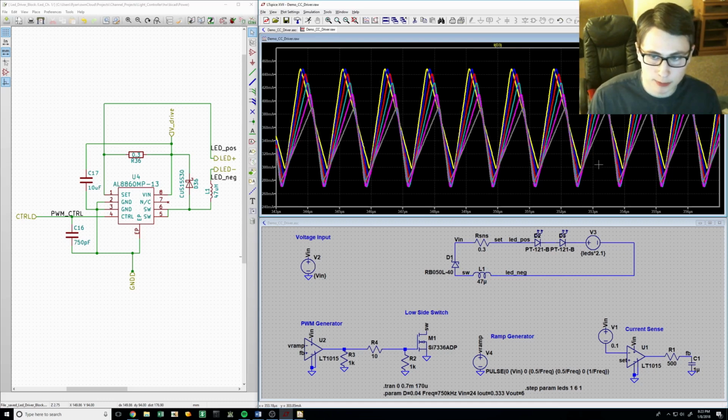It's worse than I would expect from the switch mode power supply controller we're using because it was custom built for current regulation, but it's pretty good for a couple comparators and a simple feedback configuration. Notice that it's near-centered, all of these waveforms, around our 333 milliamp set point.